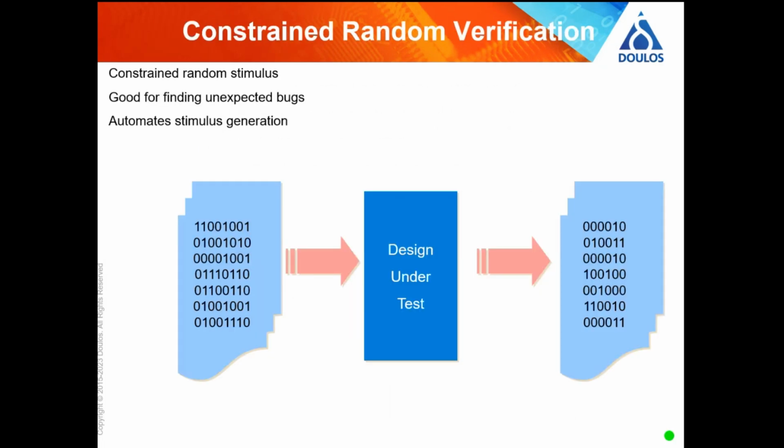So something that I've mentioned already is constrained random testing. So why might you do that? I haven't really talked about that. And the answer is mainly because it thinks of test cases you haven't thought of. So thinking of the memory again, you could think of a test for a memory.